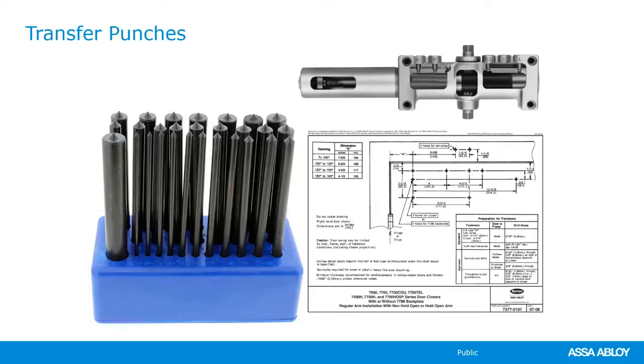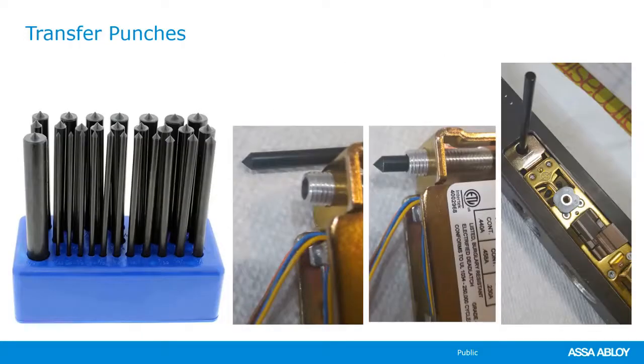Very efficient. They also work great for aluminum storefront locks. Here we have the Adams Rite Steel Hawk 4300. And let's say that this particular storefront door never had the proper mounting screws. They were using just a tension wedge to keep the lock in there. But we know that this particular lock, when it's mounted with the proper screws, lasts longer, and it stays tight. So we can use a transfer punch to mark the backside of that aluminum door and then drill it out and then tap it to the 10-32 screws that it comes with.